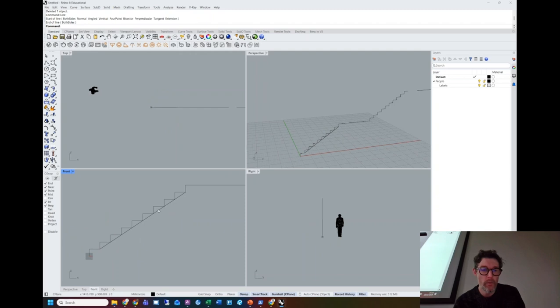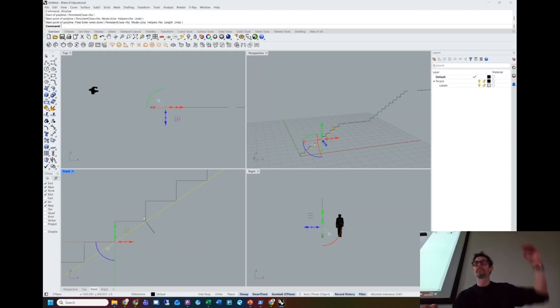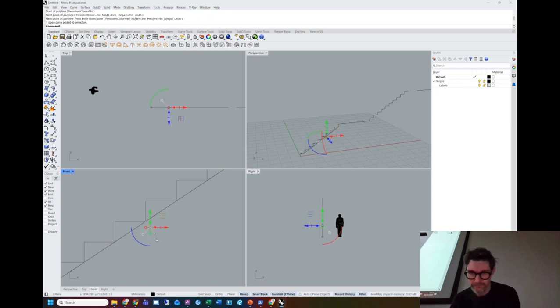And then I want to make sure that I've got control over this distance, the distance between the thinnest part of my concrete stair and where the back of it goes. Because if that's too thin, then this thing is going to crack. It's going to be too brittle. If it's too thick, I've used up far too much material. So I want to get that right. I've got a number in my mind. Maybe it's, I don't know, 100 millimeters or something. It's probably a bit less, maybe 75, but let's be generous.